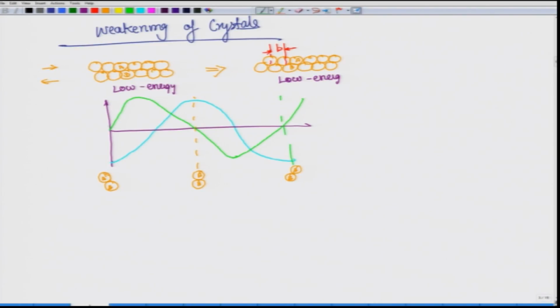So, what you can see here is that in the region where you have A and B in the lowest energy position, you have 0 stress required. When the A and B are again in the final position, then you have 0 stress required. Somewhere over here there is 0 stress, but it does not mean it is a stable position. If you just push it a little bit, then negative stress is required, or it will automatically come down to this position. This is what this plot implies.